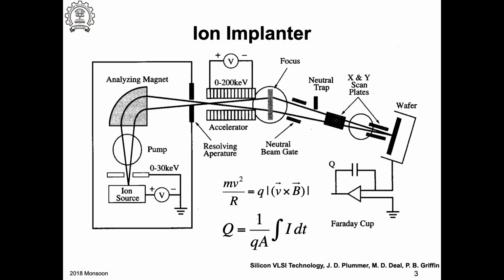Okay, so this is used for actually removing those unwanted ions from the implantation process. Then you apply this acceleration. This is where you are applying. So when you say that I'm doing a 100 kV implantation, this is what the acceleration refers to. Now, during this transport, some of these ions can get neutralized. That is possible. But before the neutralization, let's say they have been accelerated. So neutralization happens after the acceleration.